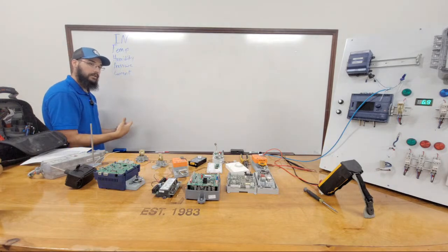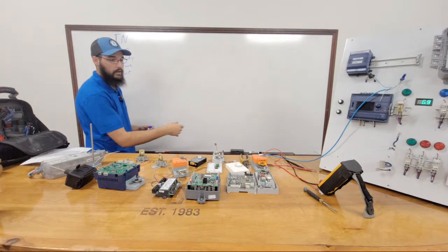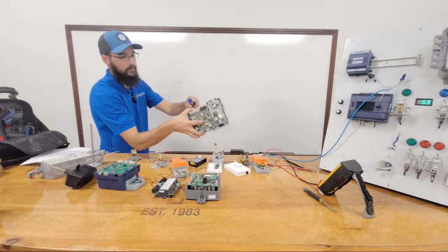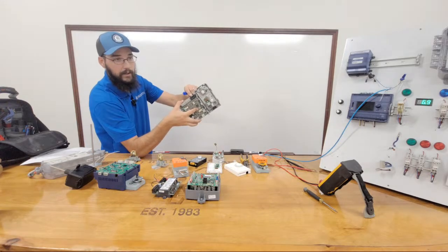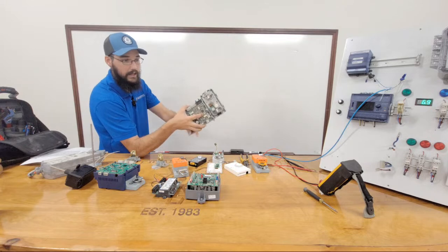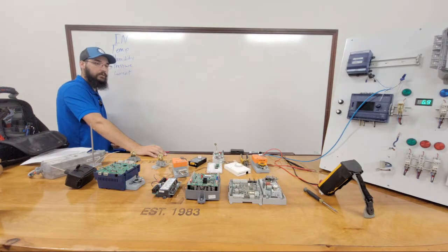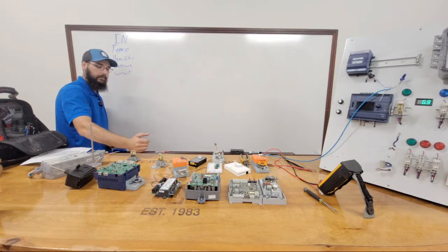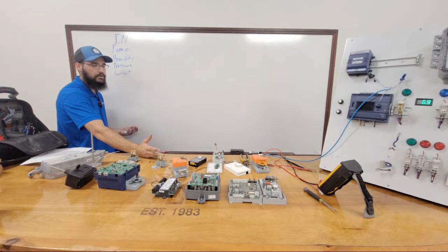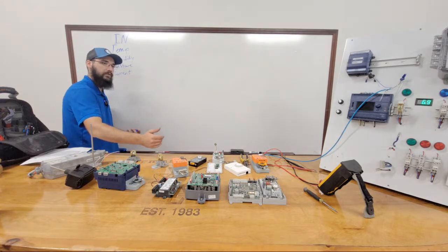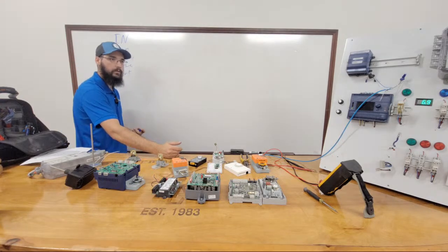Pressure is also done in multiple ways. So, for example, these would be air pressure pickups for static pressure. But ultimately, you could have a legitimate transducer, a 0 to 5 volt, or most transducers are actually 0.5 to 4.5 volts.